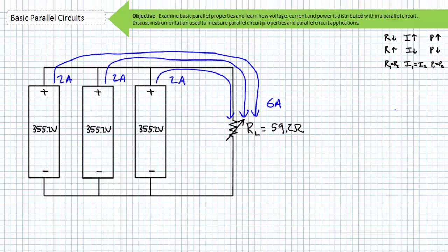Additionally, in the event of moderate current demand, each source in parallel will experience a current draw inversely proportional to the number of sources providing current. In this case, the electrical load still draws its required current from the available 355.2 volts. However, it's just drawing that current from 3 different places. Many hands make light work.